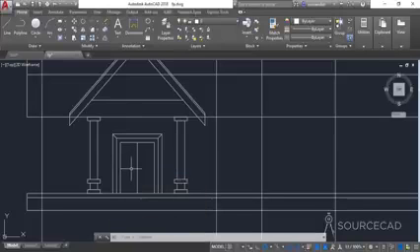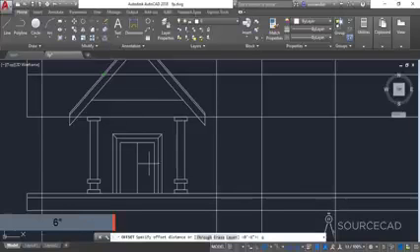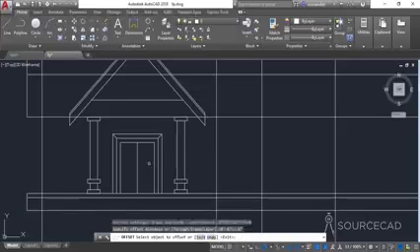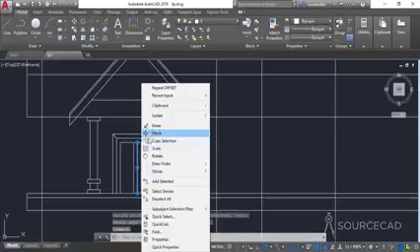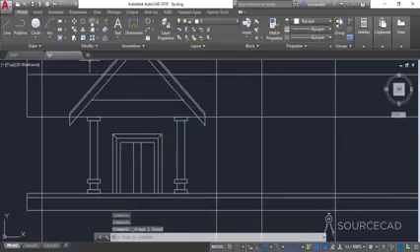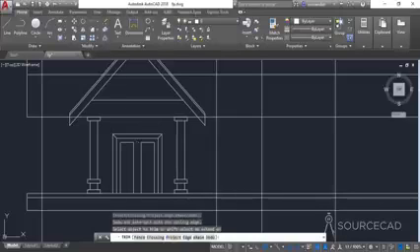And here again I'll make an offset. So I'll go to offset, and the offset distance is obviously 6 inches. Offset it towards the left and towards right. Now we can actually remove this line, and we can also trim this part. So trim and this part. So you can see that I'm adding actually a lot of details here.